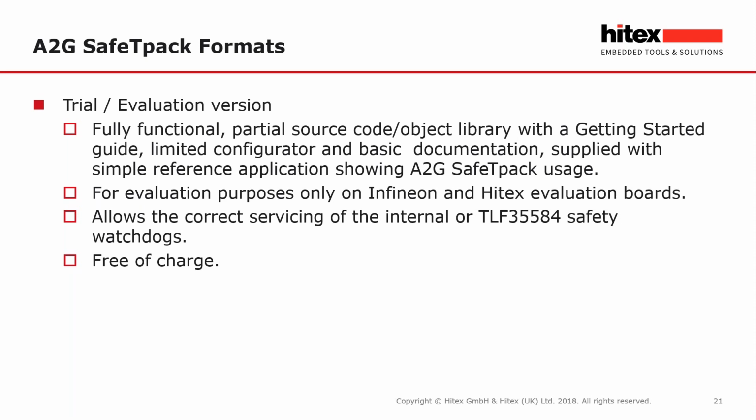It's locked so that it will only work on Infineon and Hitex evaluation boards. So this is things like the TriBoards and so on, the application kits. The key thing is that it will guarantee that the servicing of the internal watchdogs and the external TLF35584 are correct from day one, so that you can get on with developing the application without having to worry too much about how these watchdogs are being serviced.